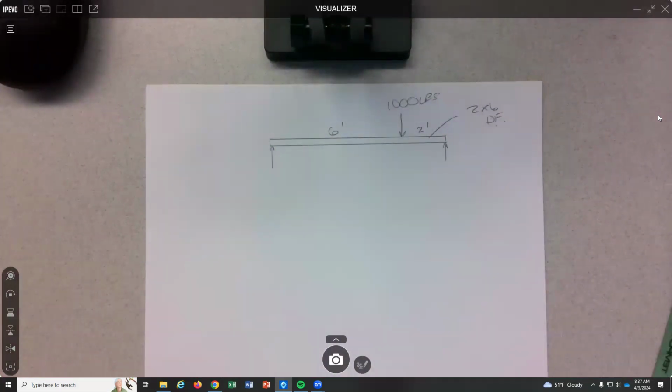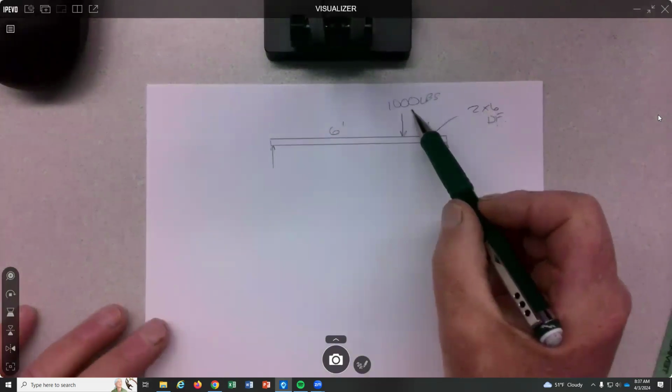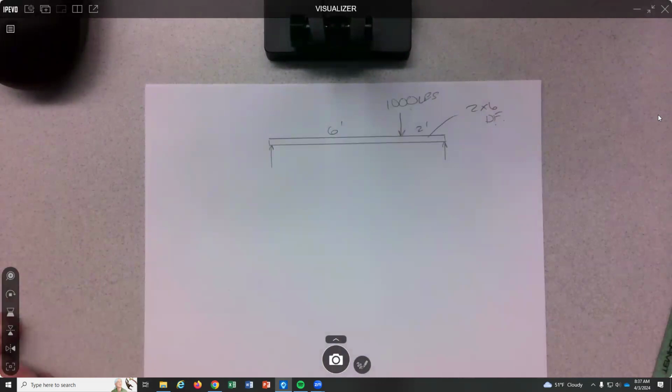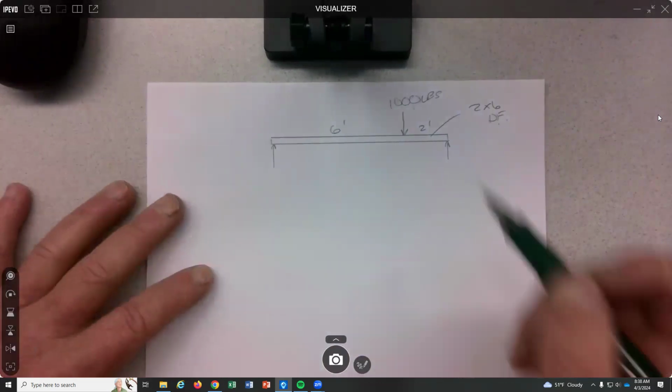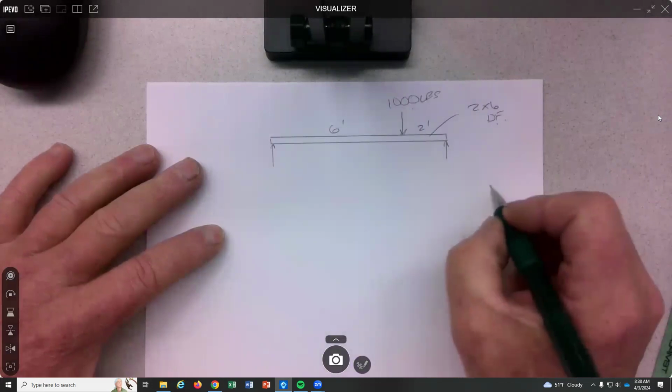All right, so it almost always is gonna start with a statics problem. This load for the project, you're gonna have to estimate loads. So with a bunch of stuff on it, I might weigh 170 pounds type of thing. But we'll put 1,000 pounds on a Doug fir 2x6. What we want to know is bending stress.